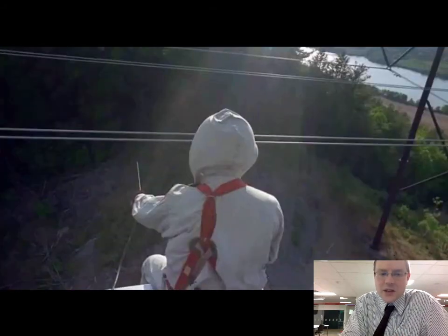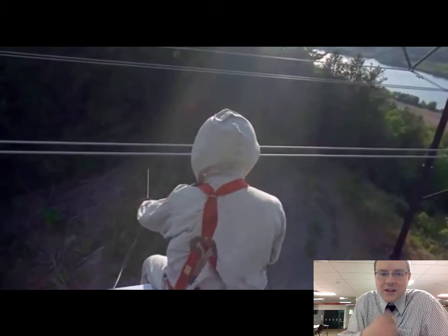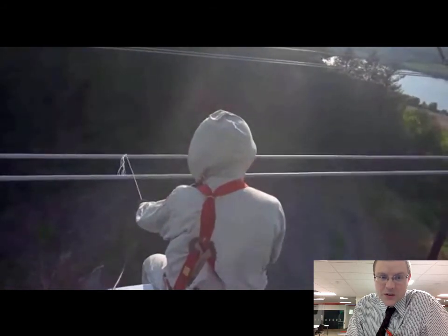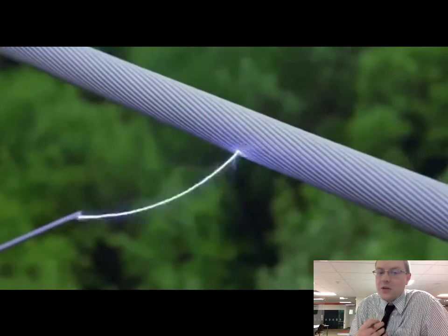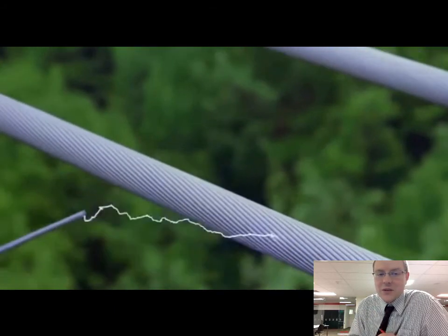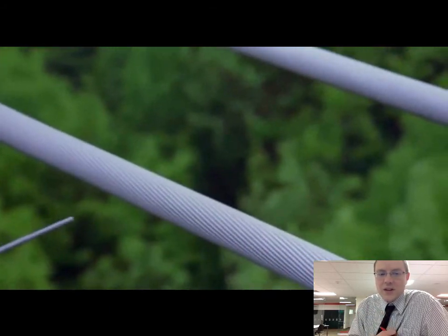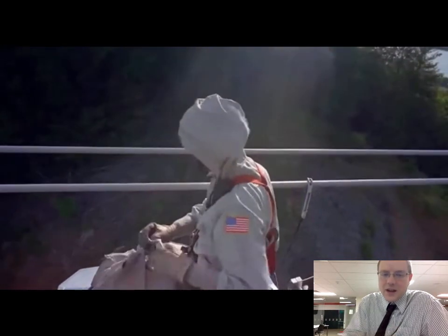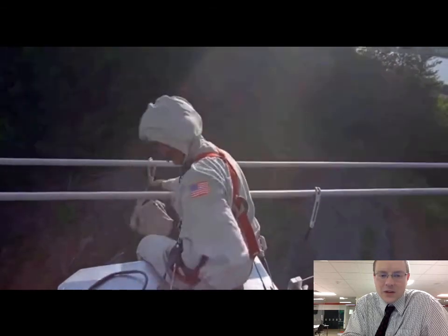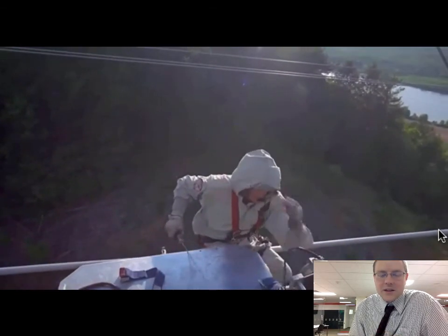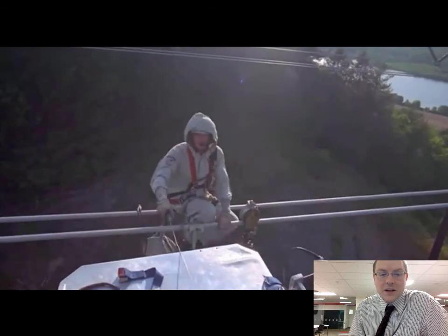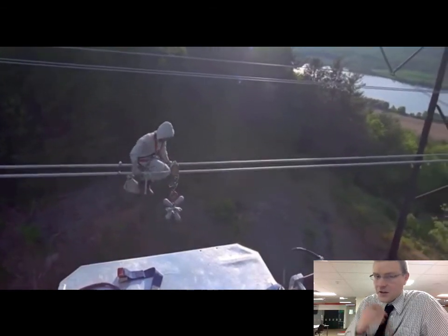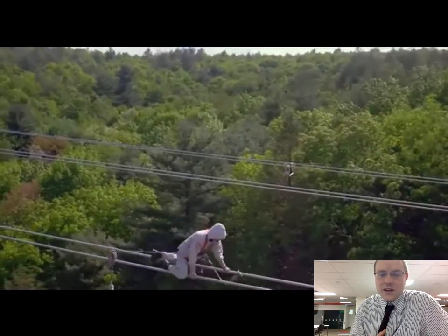They actually reach out with a Faraday suit, and you can see that the electricity raises the potential of the person and the helicopter. Since they're all metal, the person's wearing a Faraday suit and the helicopter's all metal. As soon as they are both raised to the same potential, he can touch the line, everything's good to go, and he can climb out onto that power line. Once he's on the line, he disconnects the cable from the helicopter, and you can see the helicopter flies away, the helicopter becomes de-energized without touching the ground, and the guy can walk on the line safely.